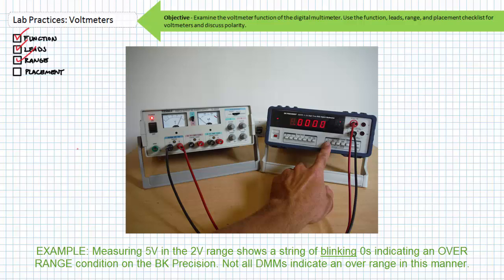Take your time and think before you act. One further consideration of range before we move on. What if we didn't know what to expect for a voltage reading other than it was below 1200 volts? My advice is to move in cautiously and work your way towards the most appropriate range.